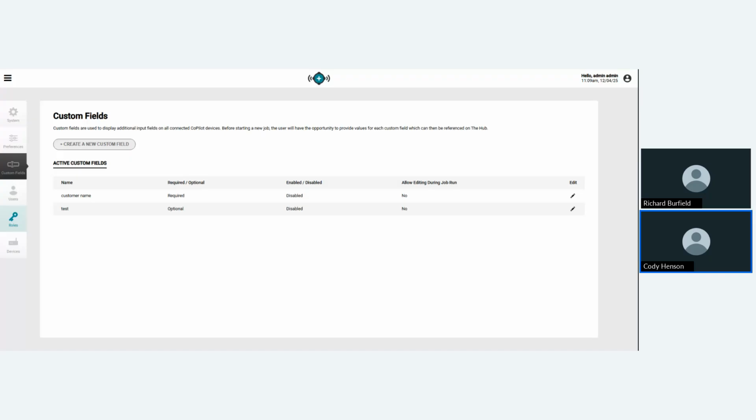If you have a large number of copilots that need an update, we would recommend that you probably just download and push them to your copilots 3 or 4 at a time. It can be a large amount of data and it's all coming from the same location. So pushing too many out can kind of bog things down and can cause some of the copilots to give a timeout alarm. So if we can keep it to just pushing out 2 to 3 at a time, or 3 to 4 at a time, we can typically avoid that timeout alarm.